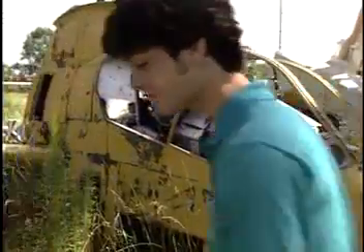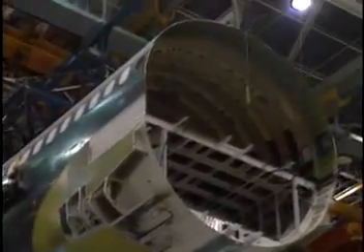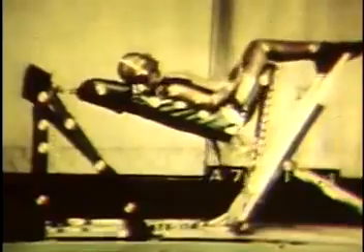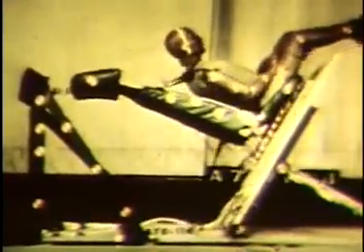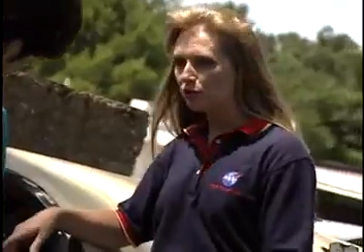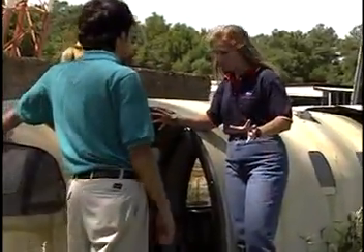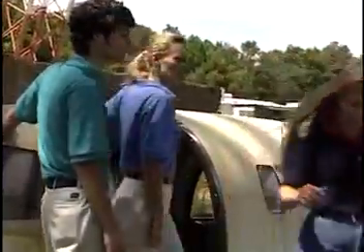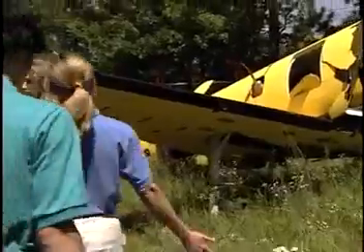Right. However, there are parts of an aircraft that can absorb energy in a crash. Parts like the subfloor, which is the area under the floor, the landing gear, the seat, and even the cushion can absorb energy. Restraints, like the seat belts, are also necessary to keep the passengers from flying through the aircraft during a crash. When these parts and structures are designed correctly, or optimized, the passengers have a better chance of surviving a crash. But Lisa, how do you design aircraft parts to absorb energy?